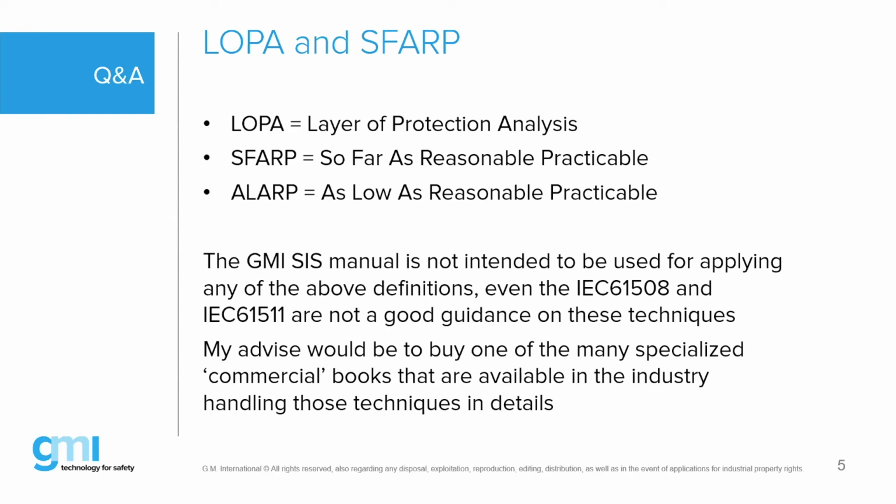If you go with a conservative approach and you have a risk model from corporate level, they say, look, when you have this type of consequence... and still I agree with you, the frequencies are always doubtful, even the frequencies of the events. But assume that your team agrees on a certain frequency with a certain consequence, it will be stated to you what type of SIL level you need. And when your risk matrix is calibrated correctly, when the team was agreeing with the corporate management, you would need a SIL 1, or go for a SIL 2 on your risk matrix, which is a very good approach. And there you will skip your LOPA and not have to actually judge those numbers so accurately.